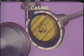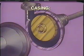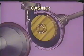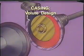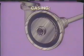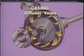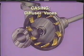A function of the casing is to reduce the velocity energy of the liquid and convert it into higher pressure. The casing shown here uses a volute design to make this conversion. Another way to convert velocity into pressure is to place diffuser vanes in the casing which slow down the flow, causing the pressure to rise.